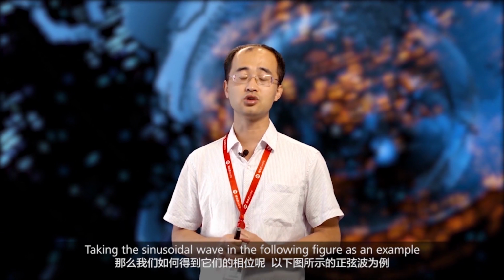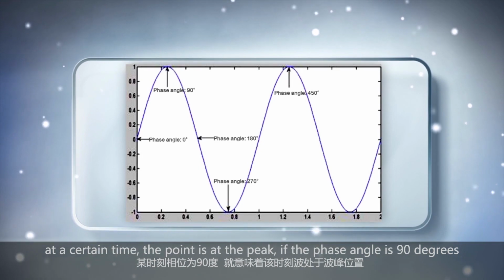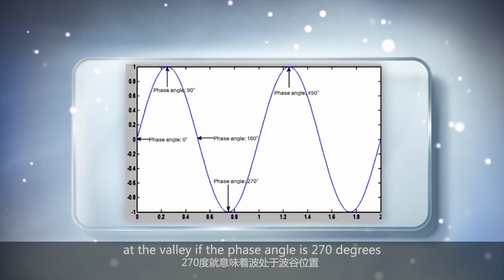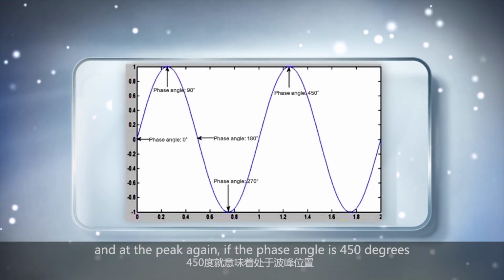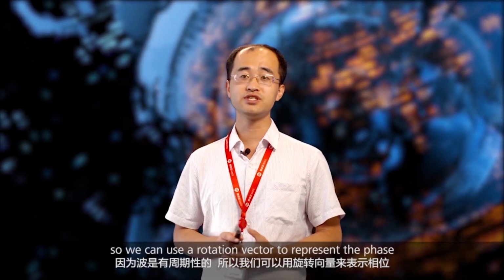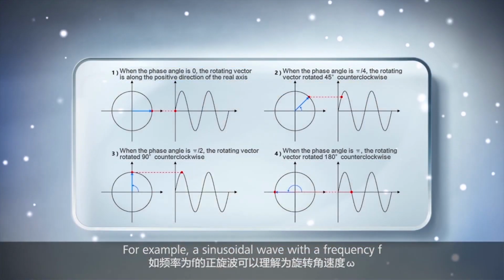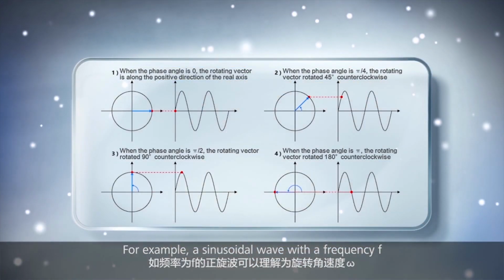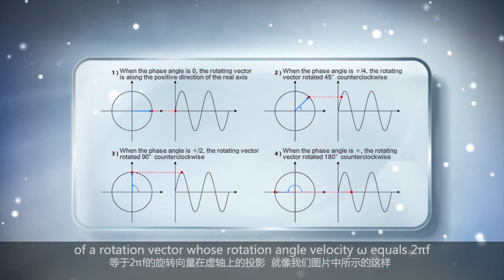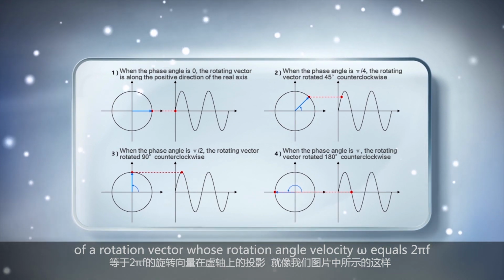Taking the sinusoidal wave in the following figure as an example, at a certain time, the point is at the peak if the phase angle is 90 degrees, at the valley if the phase angle is 270 degrees, and at the peak again if the phase angle is 450 degrees. The waves are cyclic, so we can use a rotation vector to represent the phase. For example, a sinusoidal wave with a frequency f can be understood as the projection on the imaginary axis of a rotation vector, whose rotation angle velocity omega equals 2 pi f.